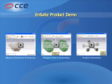Let's take a look to see how EnSuite can help with your purchasing and quality departments. Okay, it's easy to access bill of material parent and child information. You can access an indented BOM, print it, and save the BOM to an Excel file. This will help your purchasing department identify all of the components necessary directly from the native CAD file. Materials can also be assigned to each component to determine part mass for estimating purposes.